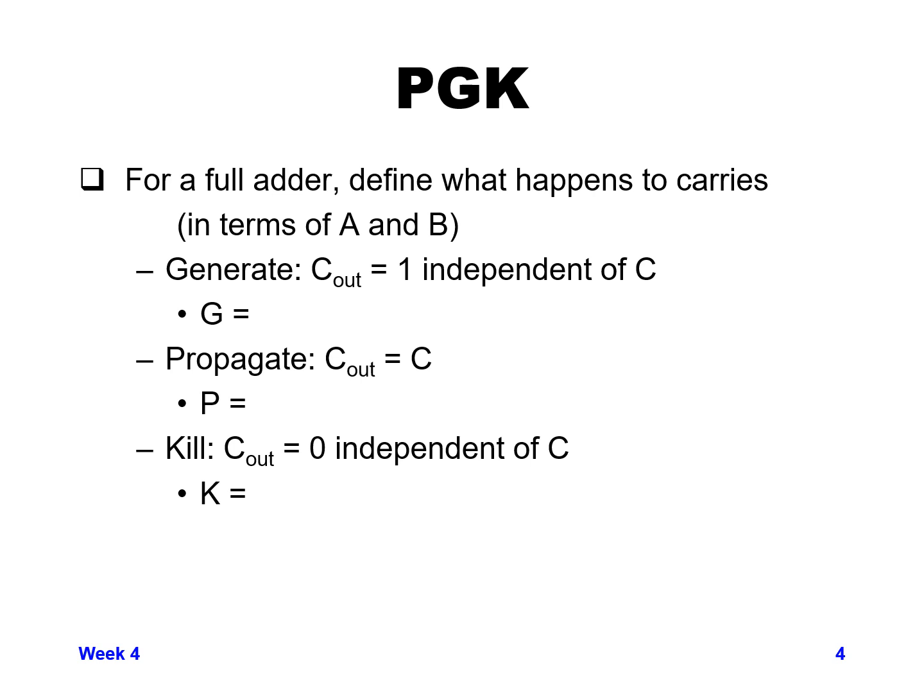They're sitting there, waiting for the carry to come in. So if we can have anything that depends on A and B, it calculates something in terms of A and B, and then we've got a value sitting there waiting for figuring out whether your carry is a 0 or your carry is a 1, and that way we can allow the carry out to go out really quickly if we pre-calculate things based on A and B. So here's where the concept of a generate, a propagate, and a kill come in.